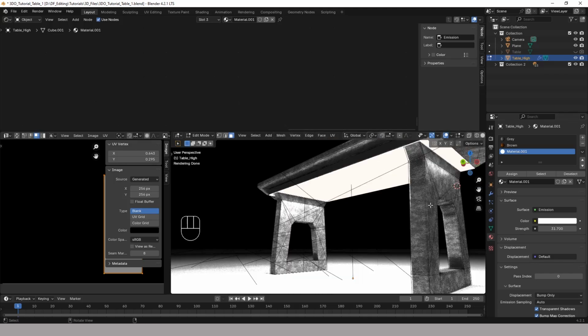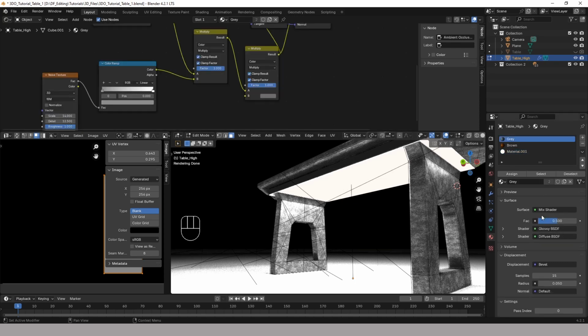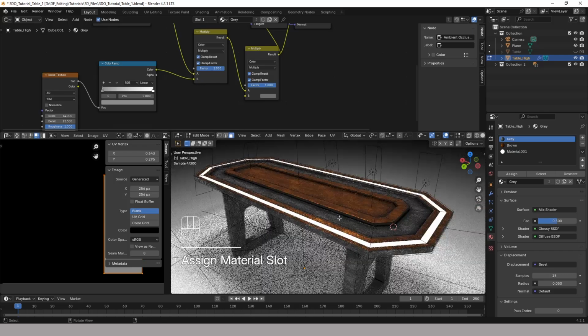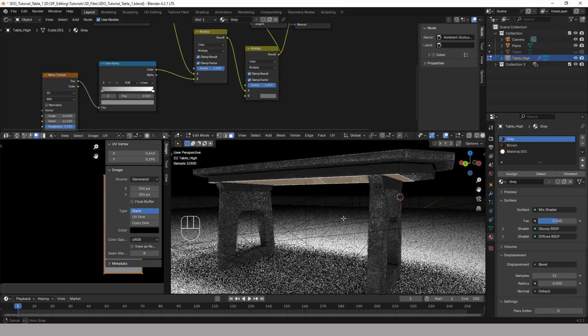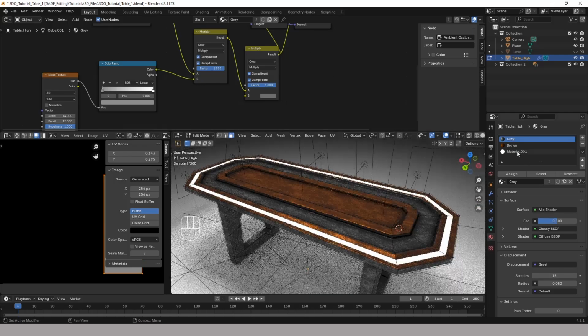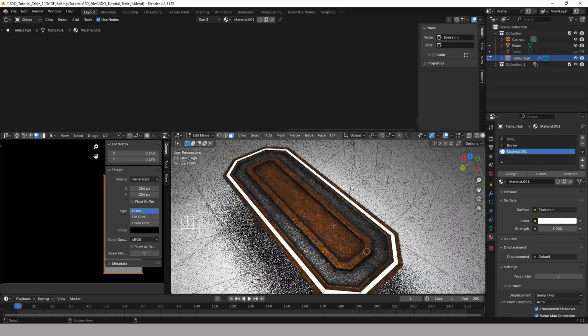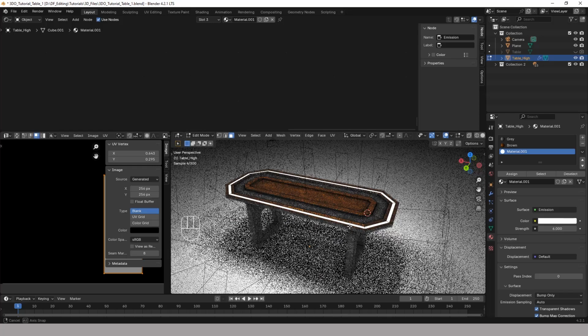But that's kind of why we're doing this texture baking method, is because you can make use of anything that Blender's renderer can do, bake it into a JPEG or a PNG, which we then convert into a texture file that can be used in Dark Forces, and we get that effect for free. It's just all part of the texture instead of actually happening in real time. So again, that value was more like 6, and away we go.